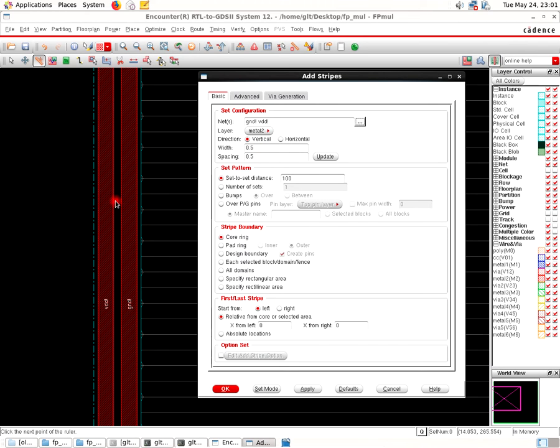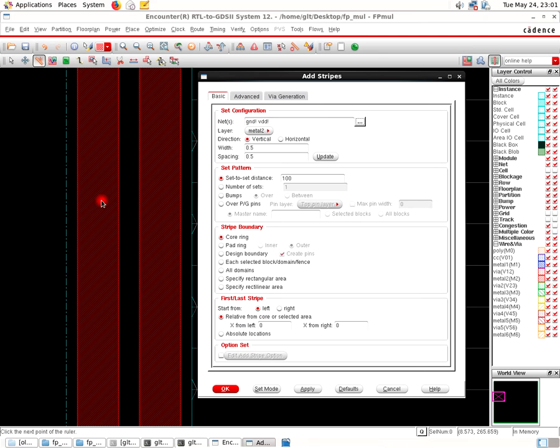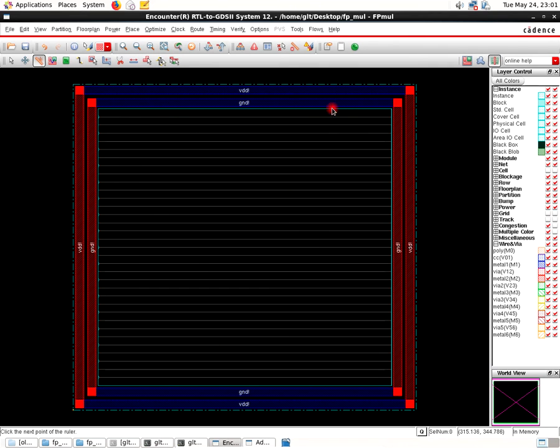So you can simply give half of this or a quarter of this. So I am just providing, sorry, not 0.3, 3 micrometer. So this is 10 and I gave 3 micrometer, and spacing, I'm going to give 1.5 microns. Okay, 1.5 microns, and see I'm planning to place around 8 to 10 strips in between this vertically.